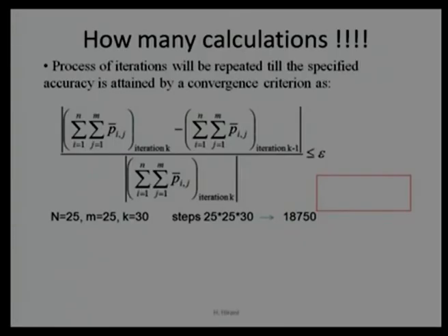It may be 1% of the pressure, 0.1% of pressure, 0.01% of pressure, depending on the order of analysis. Are we doing the final design, or are we doing the initial design? For initial design, we may not require so many iterations, we require some initial geometry, so that we can come up with some results, and then go on to check compatibility with the other components. So, what we say is that the pressure convergence term is based on the pressure.